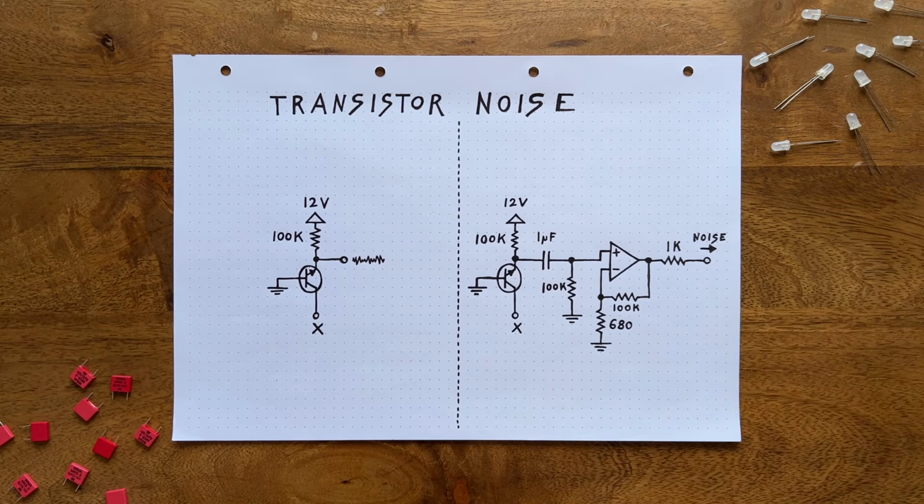Since a high-pass only allows frequencies above its cutoff frequency to pass through, this will remove the constant positive offset from our signal. Simply because a constant offset is effectively an oscillation with a frequency of 0 Hz. Now, since we want to remove as little of our noise signal as possible, we choose a capacitor-resistor combination that gives us a very low cutoff frequency of just 1.6 Hz.